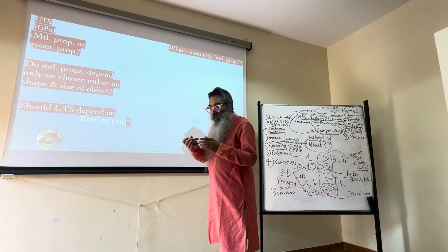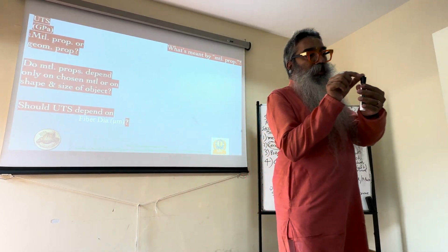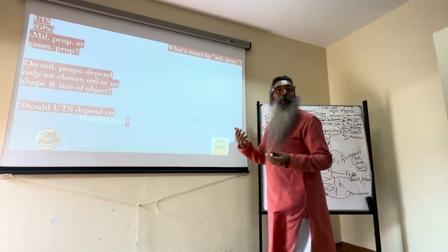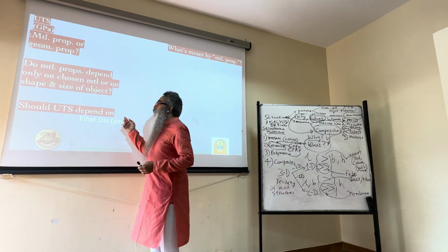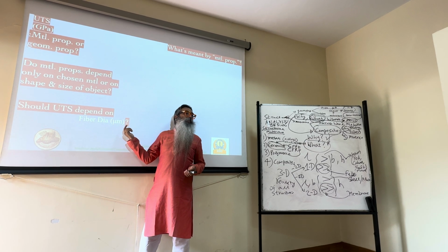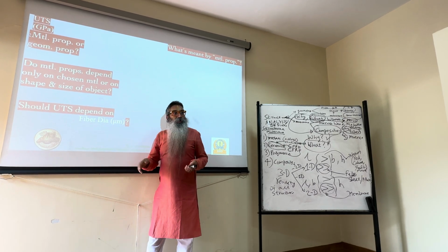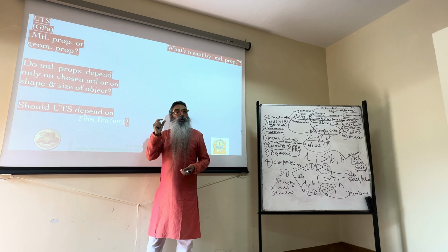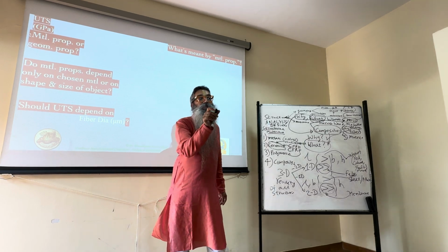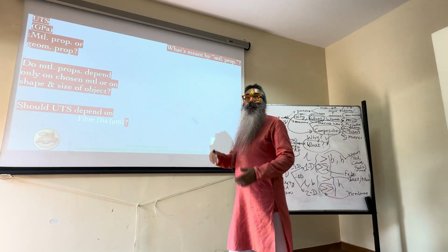So let's keep the length constant and start varying the fiber diameter. Now this has a particular diameter, let's say about 1 centimeter. Now I want to change that diameter, but in the typical dimensions of fiber diameters, which are of the order of a few microns. We saw it's typically 10 microns or so for most commercial fibers. Some fibers like boron might be thicker because they're coated fibers, like silicon carbide also. But this is of the order of a centimeter, whereas we are trying to vary the fiber diameter in the range of microns.